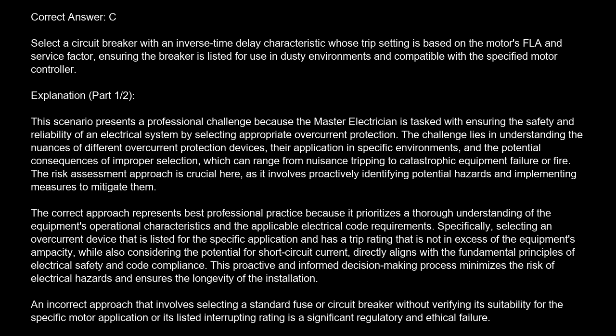The correct approach represents best professional practice because it prioritizes a thorough understanding of the equipment's operational characteristics and the applicable electrical code requirements. Specifically, selecting an overcurrent device that is listed for the specific application and has a trip rating that is not in excess of the equipment's ampacity, while also considering the potential for short-circuit current, directly aligns with the fundamental principles of electrical safety and code compliance. This proactive and informed decision-making process minimizes the risk of electrical hazards and ensures the longevity of the installation.